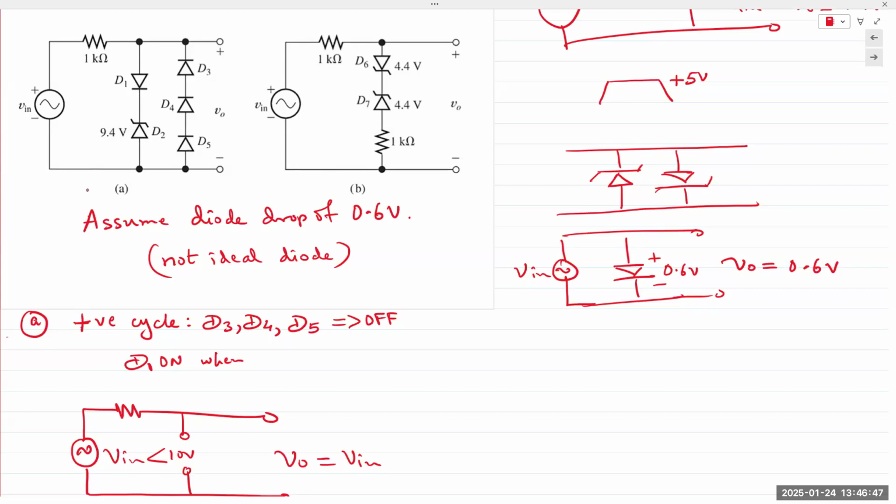That's the big difference between the two circuits. The result is still the same. We get a clipped waveform at the output. The function of the circuit is the same, but now the V in sine wave is providing the entirety of the output, but it's still a diode clipper.